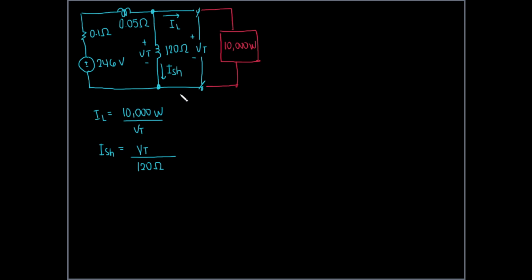And lastly, we also have what we call your armature current. Your armature current is the current passing through your armature. So if I call that IA, note from your previous basic electrical engineering course, this is a series circuit from one node to another, which means there is only one value of current passing through it. So if this is IA, then this is also IA. Now, if we write the polarity again of the drops, then this must be plus, minus. This is plus, minus.